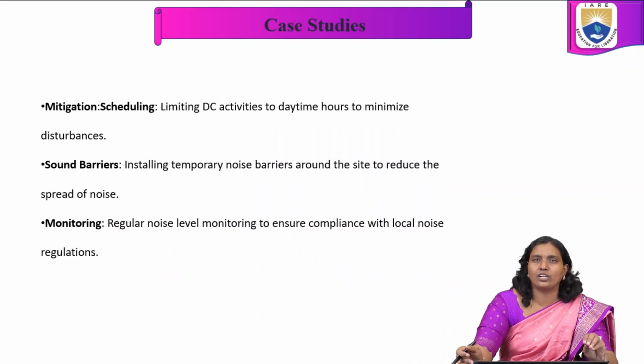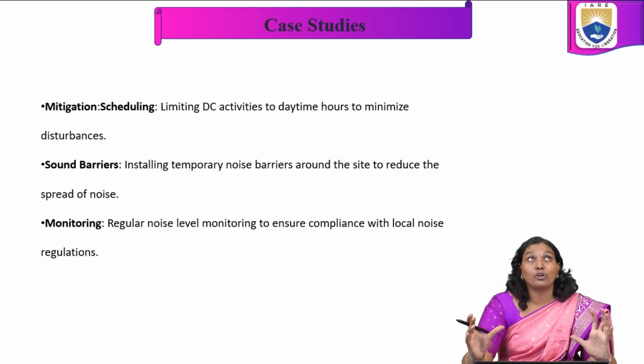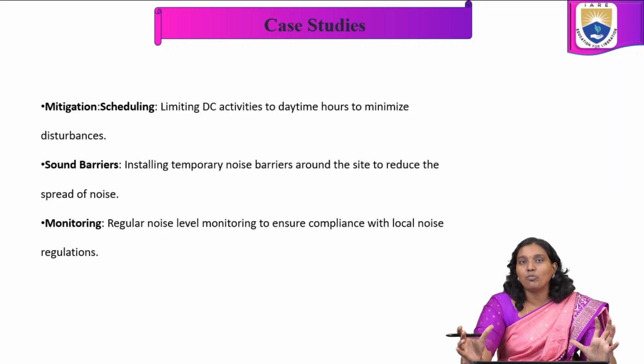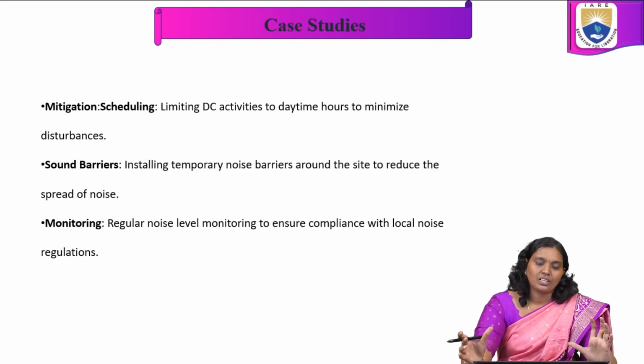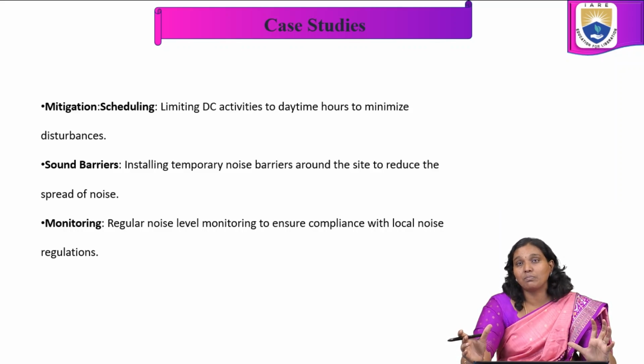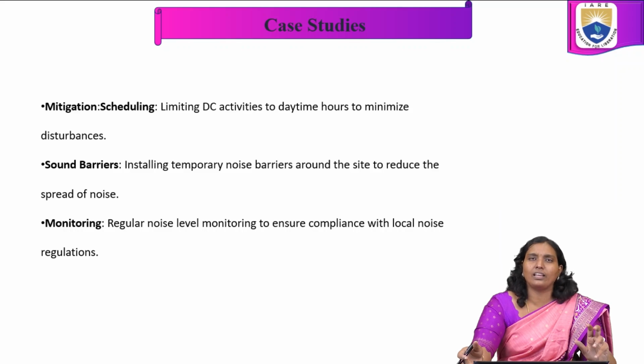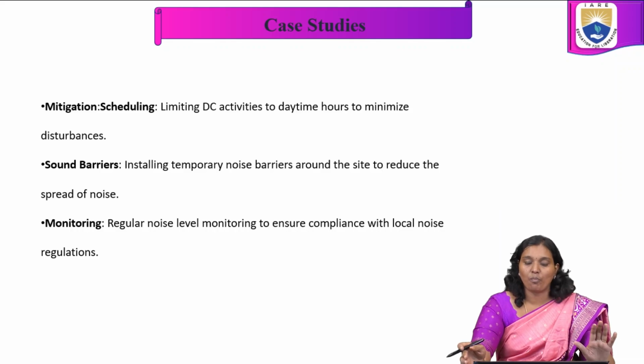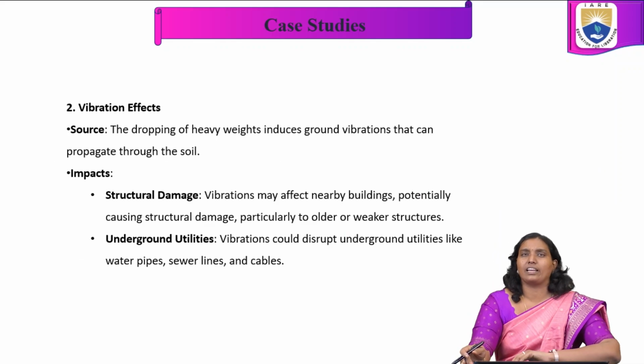In scheduling, we limit dynamic compaction activities to daytime hours to minimize these kinds of disturbances. Also, we provide sound barriers, installing temporary noise barriers around the site to reduce the spread of the noise, and regular monitoring of noise levels to ensure compliance with local noise regulations.